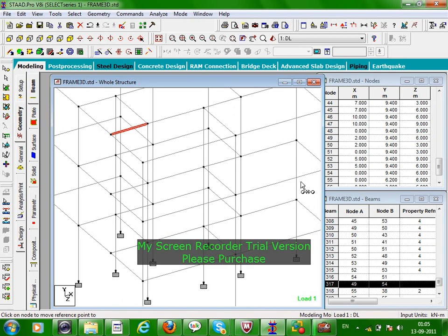So what I have done is selected the reference point of this copied beam. I have considered the reference point over here, and along this line I am finding the node where I can click and paste that beam through the reference point of this node. So I first click over here and then on this.